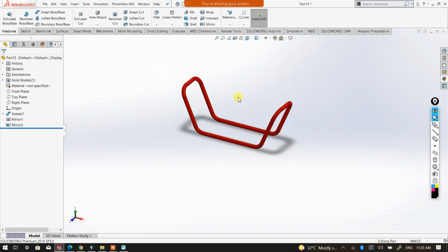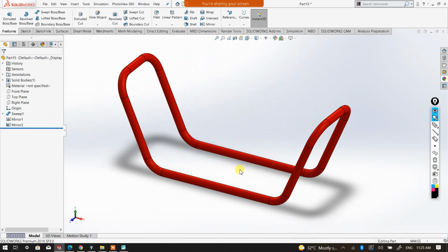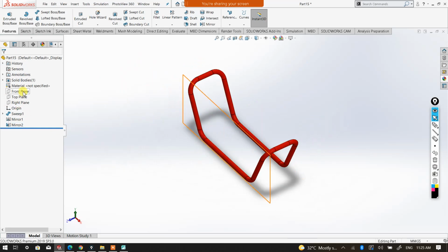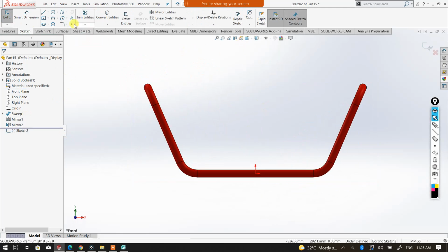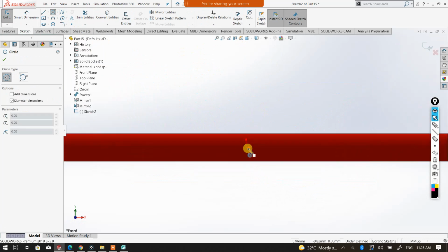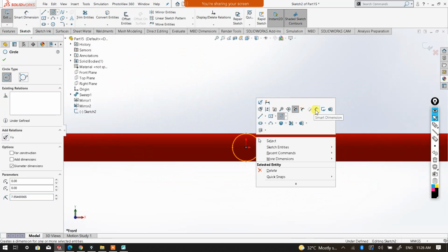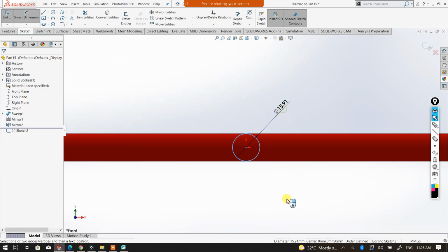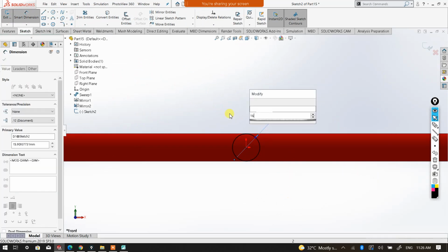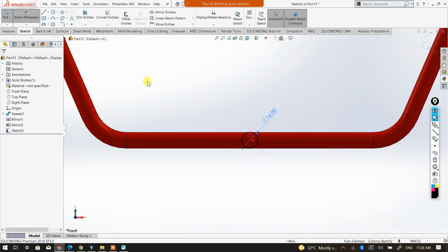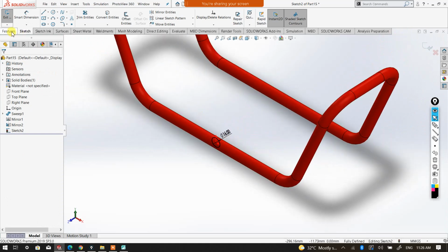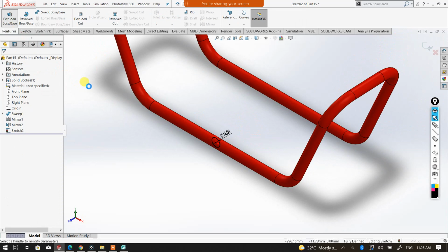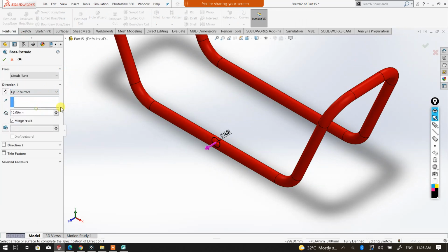Okay. So after this, you can, let's say for example, add whatever else you want. Okay, say you want to add more here, let's say for example, this is only an example, okay, ladies and gentlemen. You can have any shape or any features that you would like to have. I'm going to have 16, because the original shaft diameter is 16. Original solid shaft 16, and then I'm going to do an extruded boss up to surface. Which surface? This surface. All right. There you are.